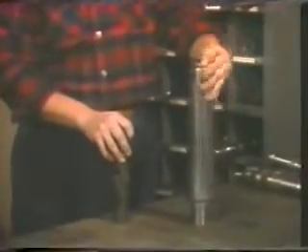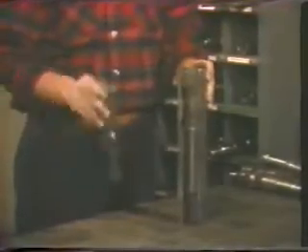or landing nipples included in the completion string. These landing nipples are designed to permit specific locking mandrels, nipple locks, to be installed in the nipples. Most subsurface controls are installed using this equipment. A landing nipple is a short section of pipe which is threaded on each end and installed as part of the tubing string during completion of the well.